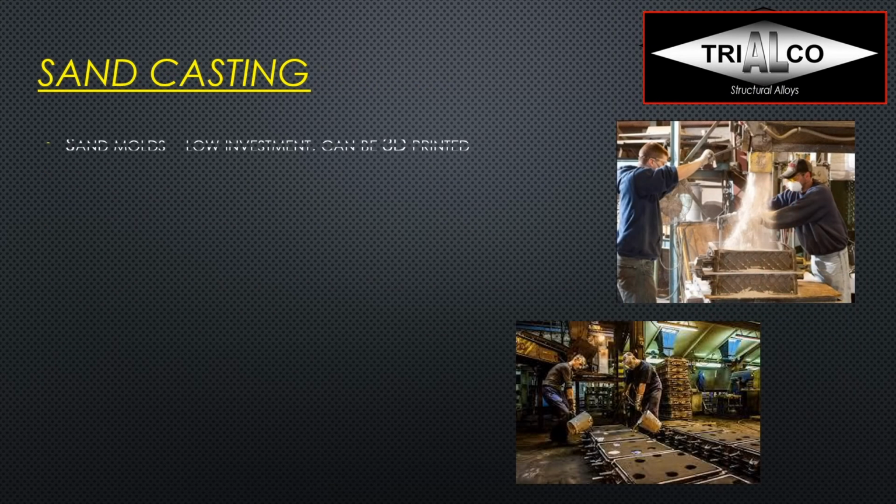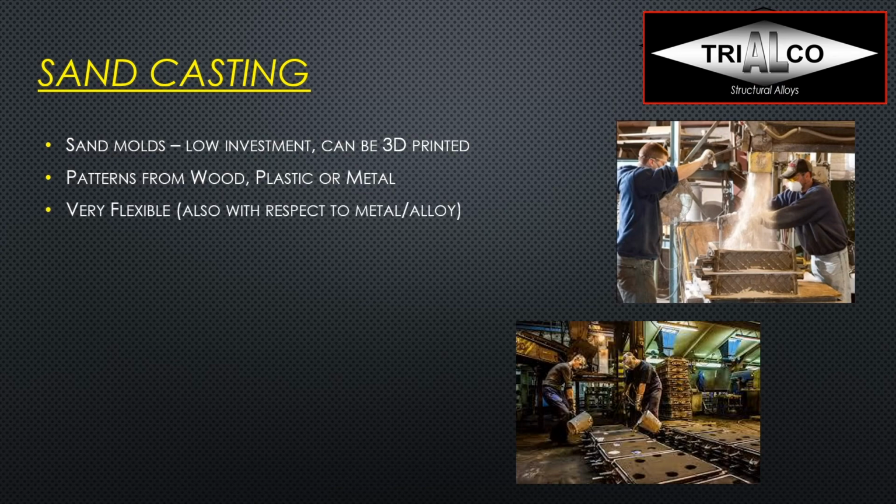Last but not least, of course, we still need to talk about sand casting. There also we see a lot of innovation, especially we now can have 3D printed molds that can be very big, which is also very interesting for making prototypes very quickly. We also know that sand molds are low investment, and that's really the big advantage here. You can have patterns made from wood, plastic, or metal if we want to reuse it many times. And the process is very flexible, also with respect to metal and alloys, so no other process would allow you to cast that many alloys.